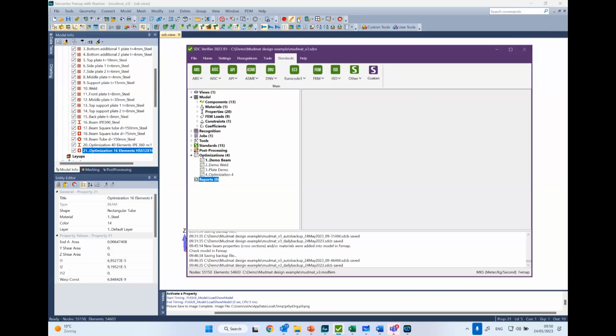But I always like to say that if the problem is simple enough to do it with beams, please model with beams. There is no reason to overcomplicate your model. If you have to do more details, do shell modeling. And if the problem is even more complicated, you're beyond the yielding limit and you want to do something non-linear and you want to do really detailed results with a good quality mesh, because solids are kind of dangerous for the FEA.